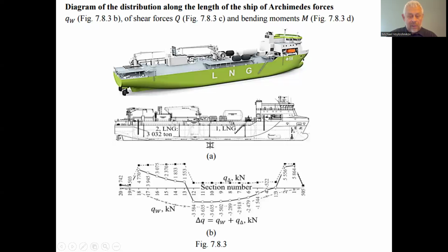So we have the cargo in just only the stern capacity distributed for 5 spacings. And we have distributed for 3 spacings of the bow ballast in the bow, to balance the trim, to exclude the inappropriate trim, and to exclude the slamming of the hull against the water when the ship is inappropriately trimmed to the aft with absence of the middle part of the cargo in the capacity number 1.